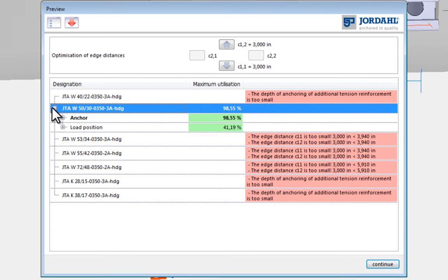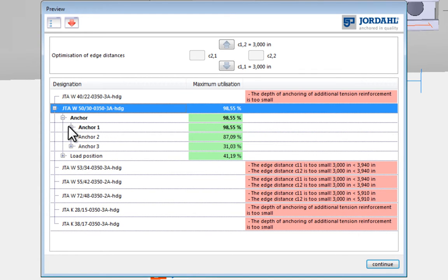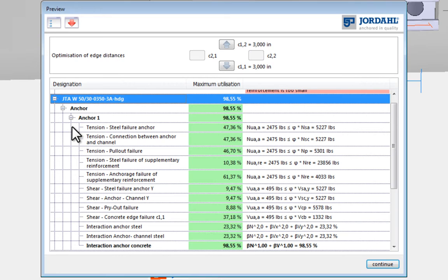The limiting failure mode is shown if the emphasized analyses are followed by pressing the plus key. In this case, this is anchorage failure in the supplementary reinforcement under tensile loads. The overall utilization is given in the interaction in conjunction with the critical failure case under shear loading. Next, a suitable T-bolt is selected.